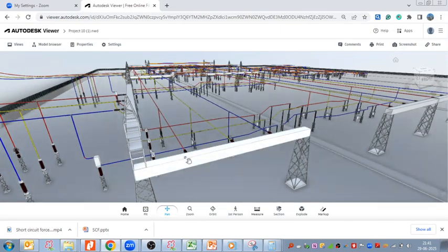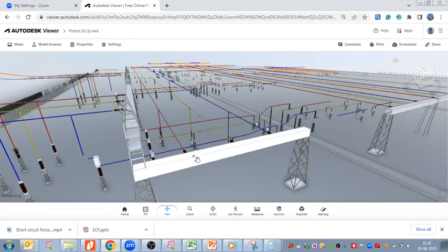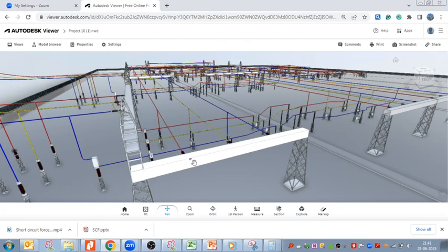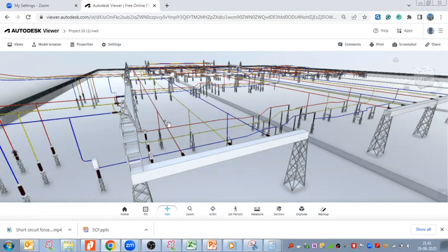Right, right. So that is exactly what I'm trying to understand. That 4 tons corresponds to the tension of the conductor, not the weight. In that tension, your conductor weight is automatically considered, because that tension means the force. This force is coming due to conductor self weight plus the force due to gravitational on the conductor. So the conductor weight is automatically considered here, sir. Okay.